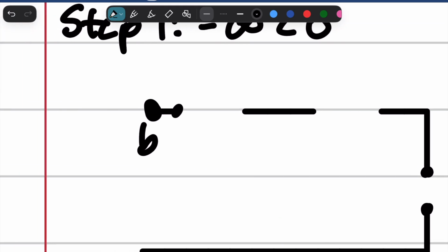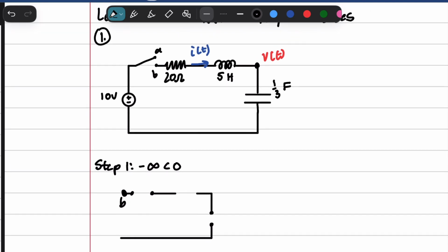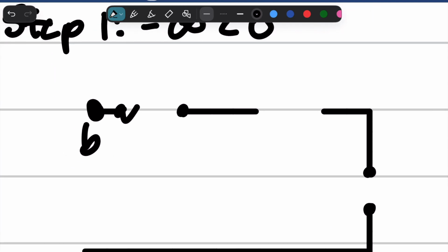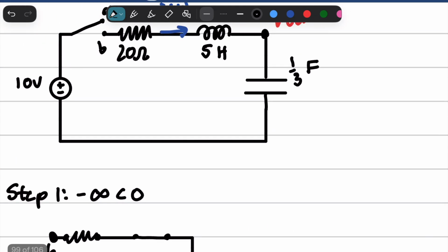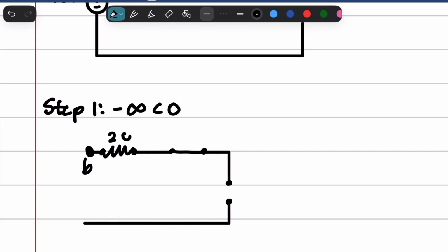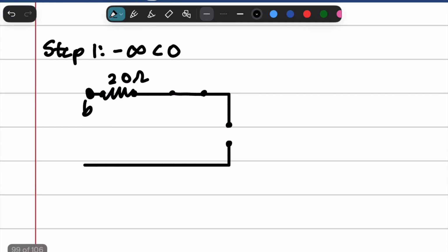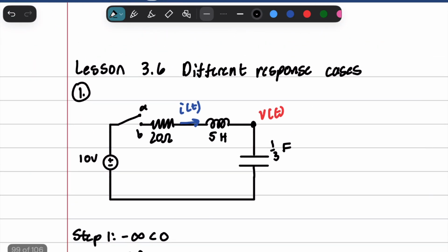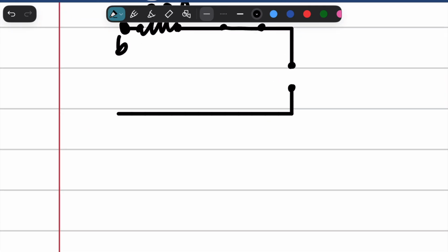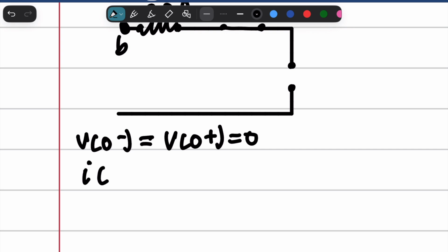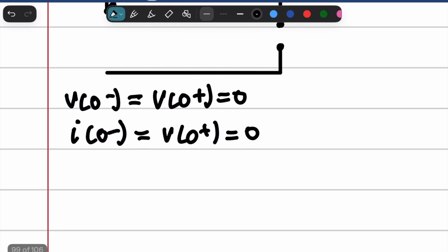And this part right here is the resistor, and right here is the inductor, like so. So 20 ohms right here. Now that's not really important because there's evidently nothing going through here. So our initial conditions are just 0 across the board, which is very lucky for us. We have no forced response when we go into the transient phase, so nothing is driving it. It's just going to start from the origin.